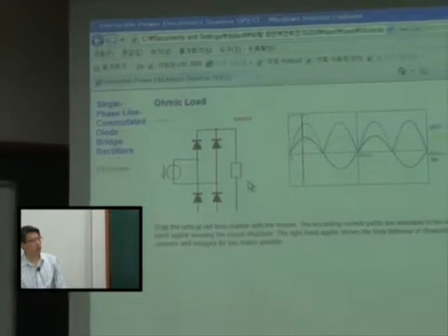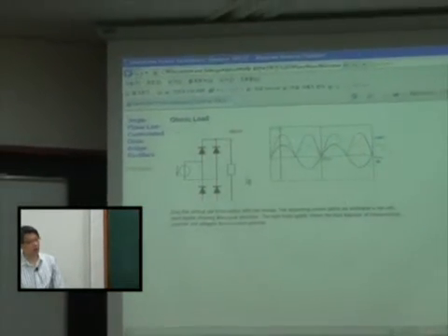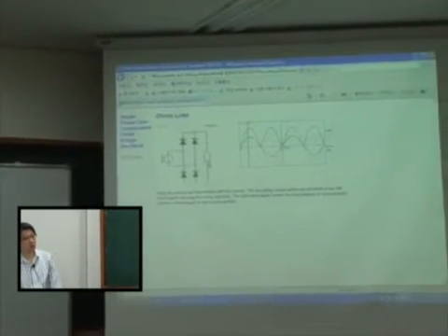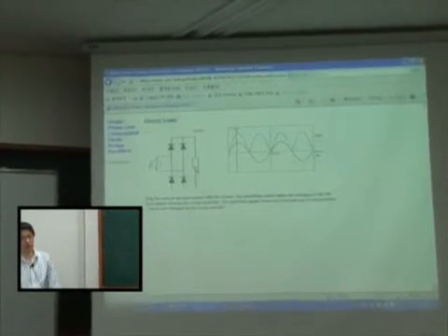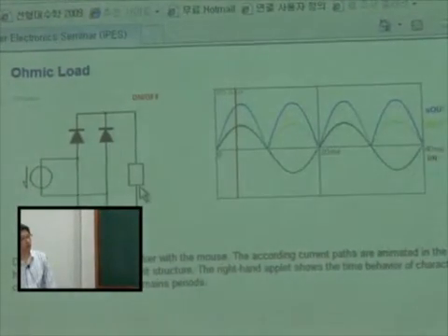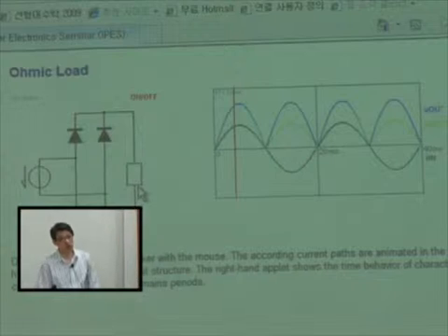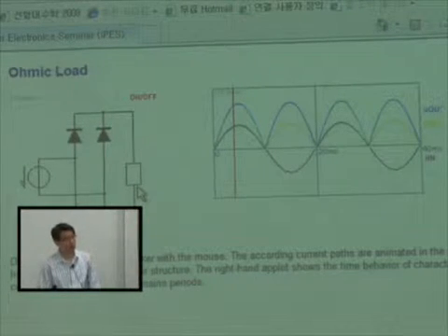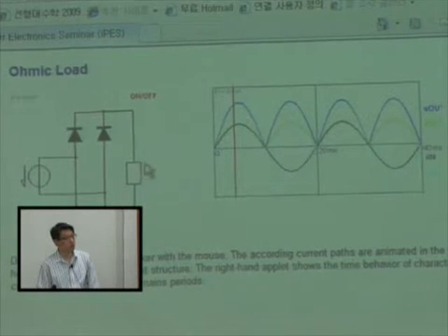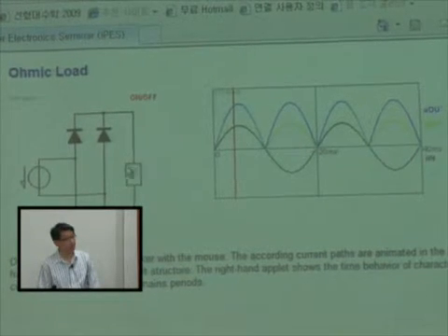When we have a motor drive connected downstream, when we learn inverters in the next class, that inverter-driven motor load can be modeled as a current source. But most DC-DC converters are modeled by resistance here.